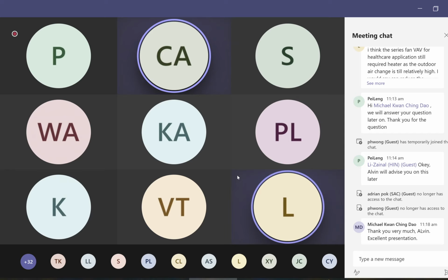So you ramp down based on the flow rate, and you cannot achieve it. Normally we base on a static control. So there might be certain areas that have over airflow. Right. If you're using pressure independent VAV boxes, you won't get underflow or overflow. Then where is the flow that is supplied to? If you're using pressure independent, you will just provide that set flow as long as there's sufficient static pressure in the duct to satisfy all the VAV.